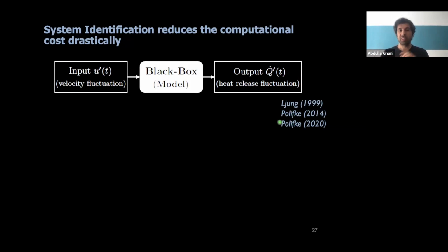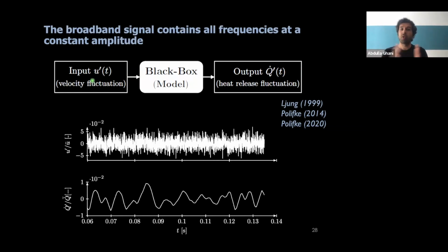So what happens here is that we don't use a U prime signal that we generate as a post-processing step, which contains one single frequency, but instead we're generating something which has multiple frequencies. So it's a broadband signal. It's containing a range of frequencies. That's why this signal is not looking anymore like a single sine wave, but it contains multiple frequencies, and then it's looking like this. This is the input signal.